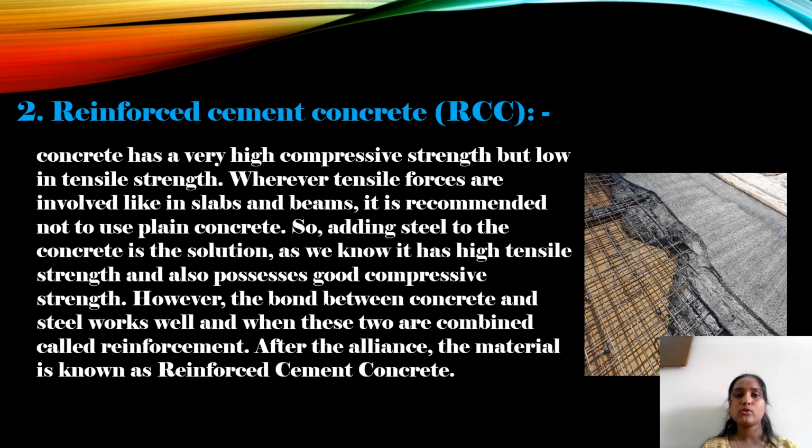Second one is reinforced cement concrete, also known as RCC. Concrete has very high compressive strength but low tensile strength. Wherever tensile forces are involved, like in slabs and beams, it is recommended not to use plain concrete. So adding steel to the concrete is the solution, as steel has high tensile strength and also possesses good compressive strength. The bond between the concrete and steel works well, and when these two are combined, the material is known as reinforced cement concrete.